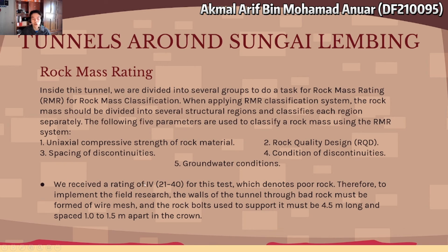So we received a rating of 21 to 40 for this test, which denotes poor rock. Therefore, to implement the field research, the walls of the tunnel through bedrock must be supported with wire mesh, and the rock bolts used to support it must be 4.5 meters long and spaced 1.0 to 1.5 meters apart in the ground.